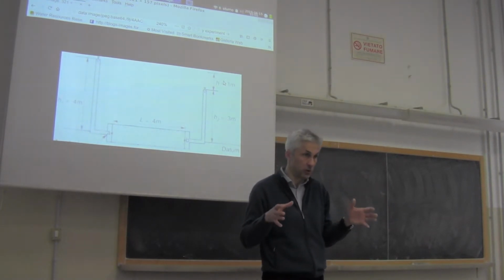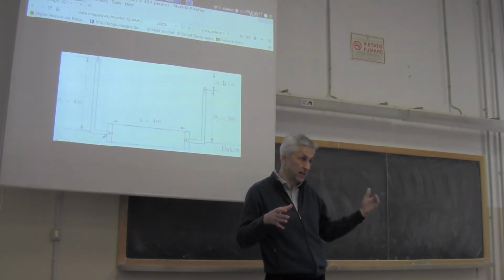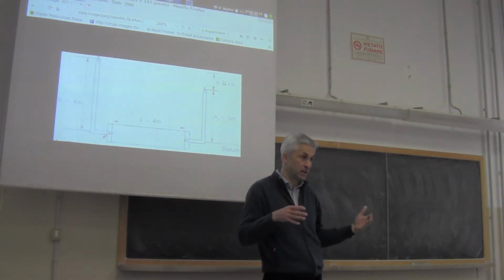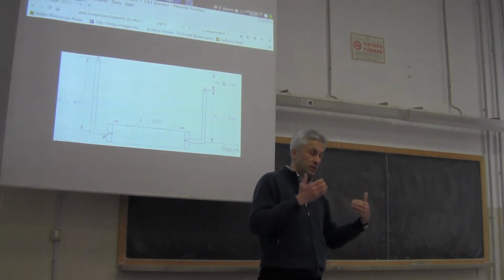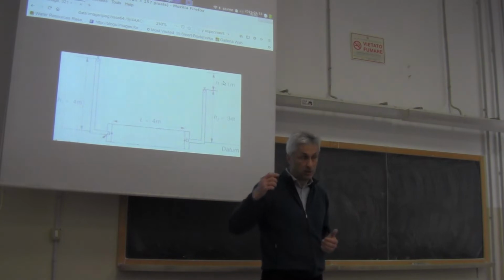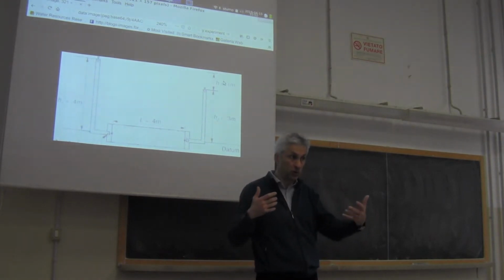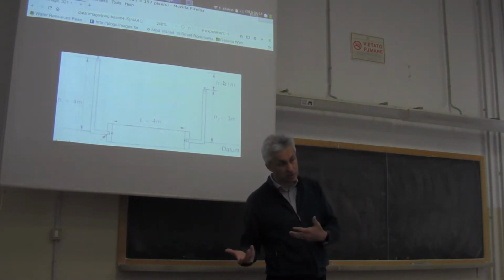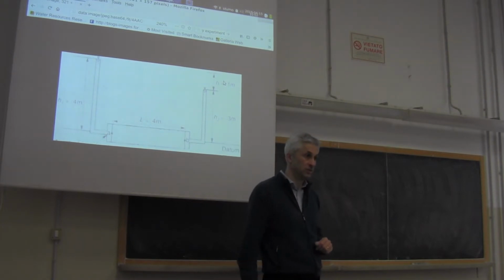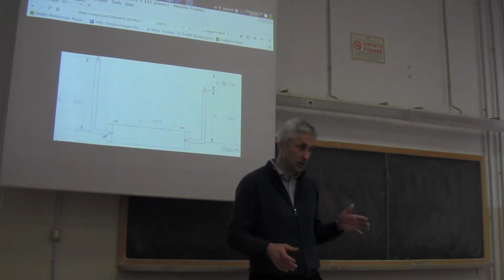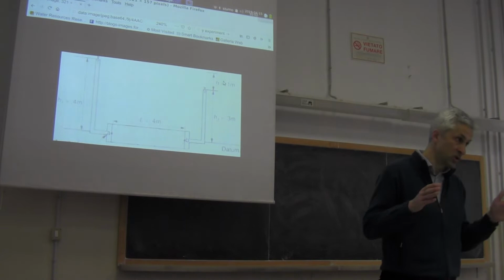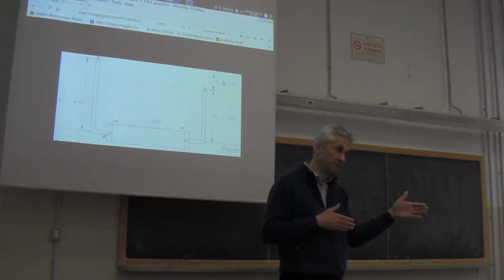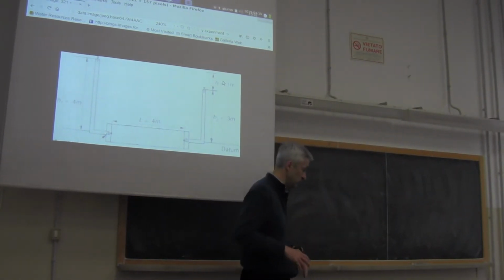In the viscous flow, you may remember from fluid mechanics, there is a linear relationship between the velocity, which means also the discharge of the flow, and change of energy losses. When the flow is laminar, when the flow is very slow, I have a linear relationship between change in energy and flow. This is what he found.